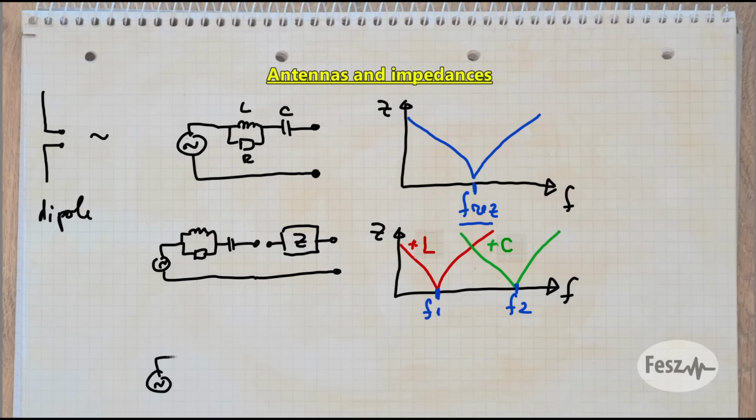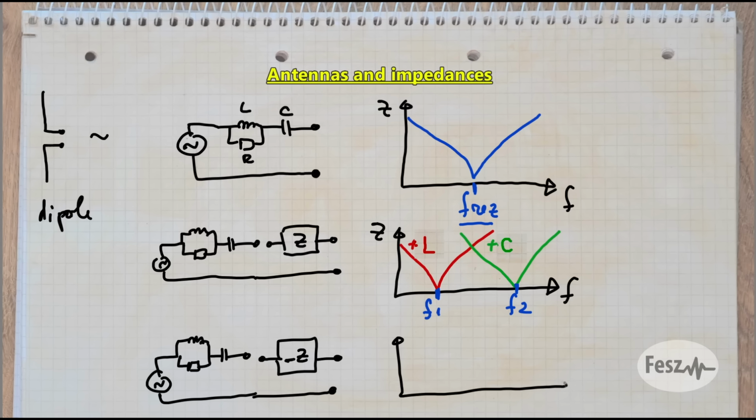Now, with negative impedance components, we are getting a new behavior. You can completely cancel out the capacitance using a negative capacitor, or the inductance using a negative inductor. In essence, producing a flat response circuit, something that could be efficiently matched over a very wide bandwidth. Now, this is not just a mathematical oddity. It has been proven to work quite a long time ago.